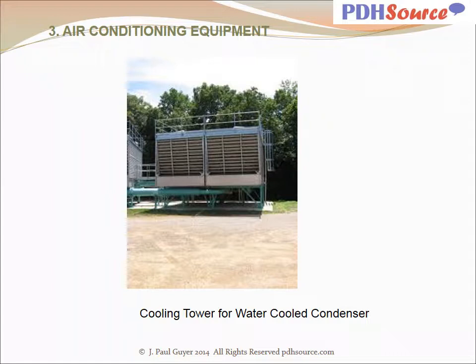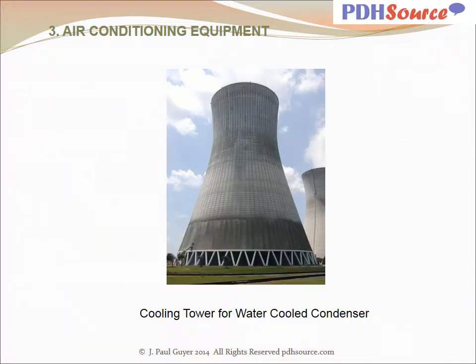Here are some photographs of cooling towers so you can get a feel. These are not small pieces of equipment, and so you don't use them on small systems. You use air-cooled condensers rather than water-cooled condensers. These are also high maintenance items, so it's just not economical to use a water-cooled condenser on a small air conditioning system.